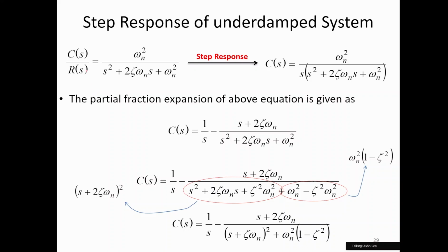And in this particular case, when you talk about a step input and you are talking about a frequency domain, you know that the input is not in the time domain, it is in the frequency domain. For an input of 1 in the time domain, in the frequency domain, the expression becomes 1 over s, right? If you remember when we talked about the Laplace transformation, when we take a Laplace transformation of a unit function, you get in the frequency domain 1 over s. And this is the transfer function. So your output for a step input is going to be 1 over s times the transfer function. So this is basically going to be the output for a unit step input.